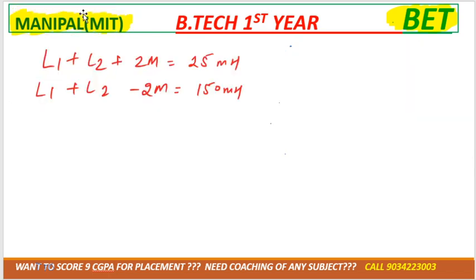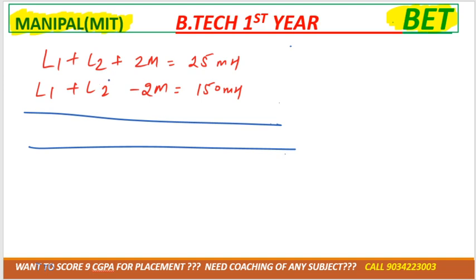Then after, how we can solve this equation? Can we add these 2 equation? So after adding these 2 equation, 2m cancels. So that would be twice of L1 plus L2 is equals to 250 plus 150 millihenry.